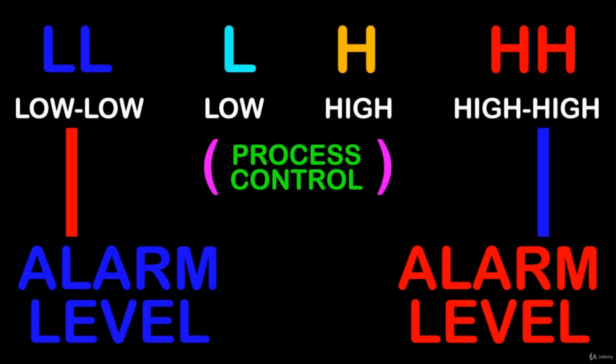Likewise, sometimes relays stick, and generally when we're energizing an output from our PLC, that output signal is actually going to a relay which is controlling the higher voltage and or higher amperage which is going to the actual device itself. And perhaps our output to the heater has de-energized, but the relay was stuck closed, in which case the heater, even though there was no output signal from our PLC, still had power and kept heating.